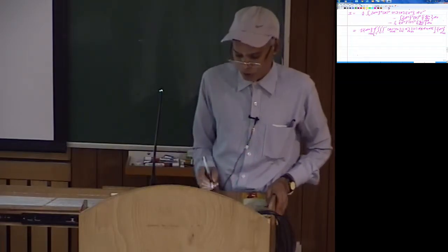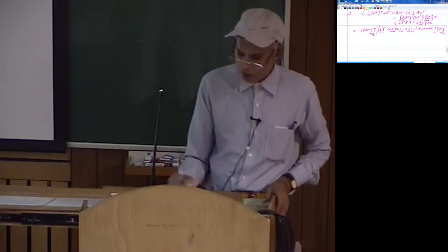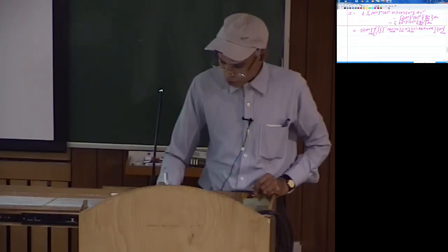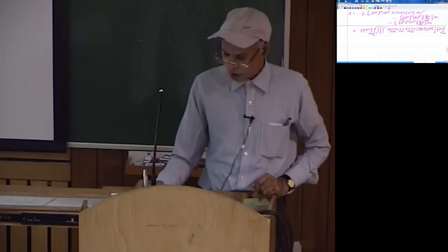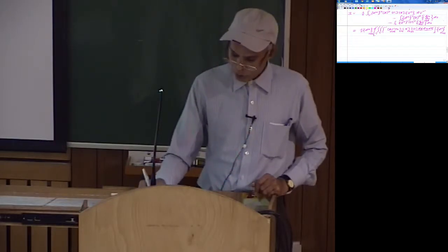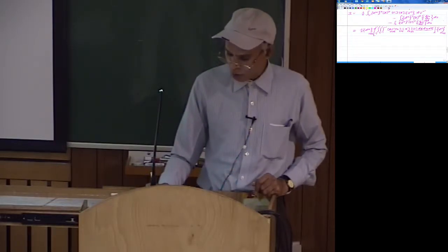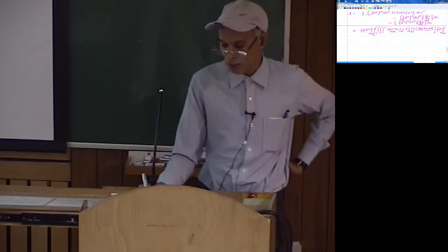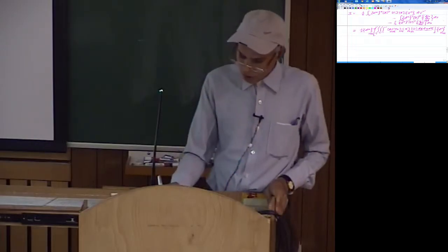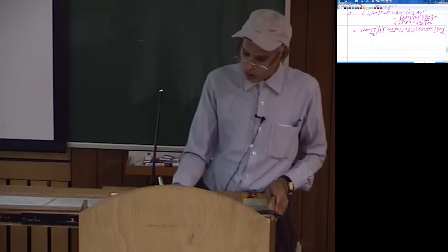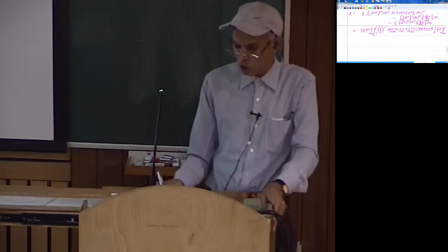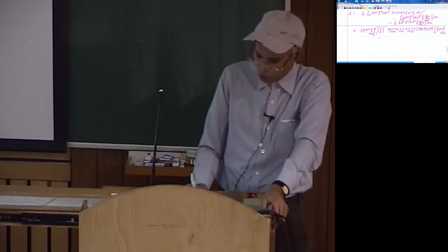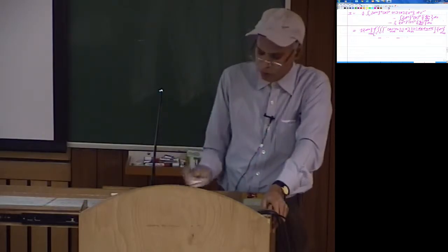So this is the first term, and the volume integral, as I said, we are now writing in terms of the natural coordinates. The way we did for 2D, similarly for 3D, we now have dV in the physical coordinate space equal to determinant J times the differential volume in the natural coordinate space, d xi, d eta and d zeta. Then similarly in this you can take out your dE transpose common, then you have H transpose fBx, fBy, fBz dV, and the last term. So the other two terms are basically handled in a similar manner.